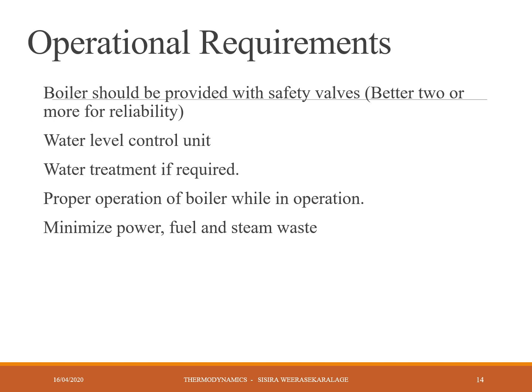This should be there. The next one is that water should be treated, because water is always inside the boiler or inside the tubes, and scaling as well as corrosion could take place. Therefore water should be treated. According to the condition of the water, the pH and alkalinity, that means calcium, magnesium and many other factors, are to be tested. Therefore, sometimes water treatment is required. It depends.